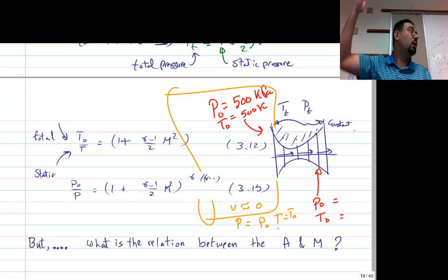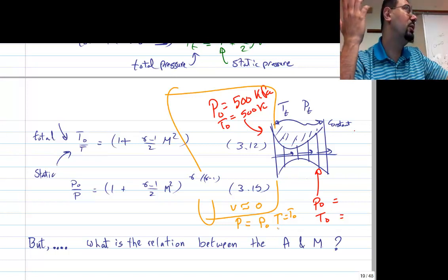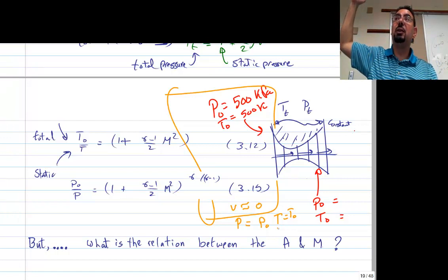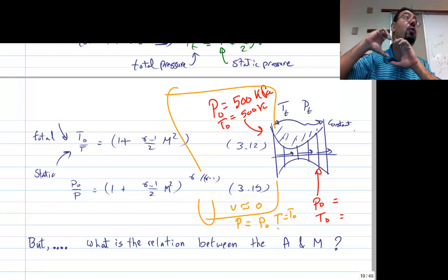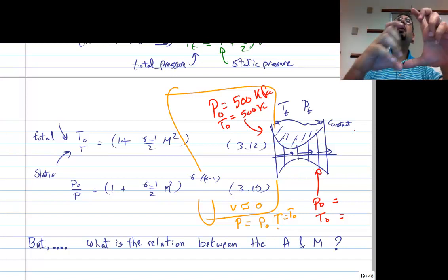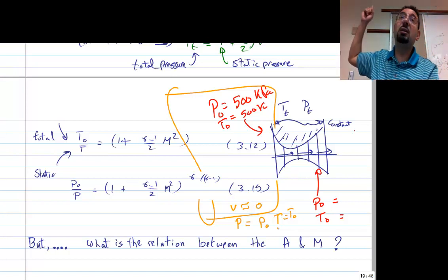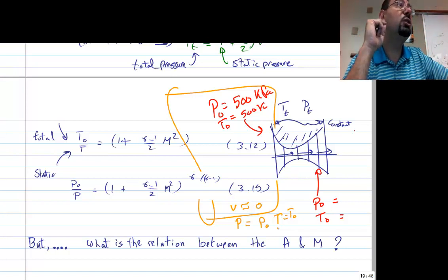So the pressure here is not stagnation pressure, right? The stagnation pressure is much higher than that pressure. You get that stagnation pressure if you slow down that air, because that's the pressure of the moving air. It's not the stagnation pressure and stagnation temperature because it's moving.